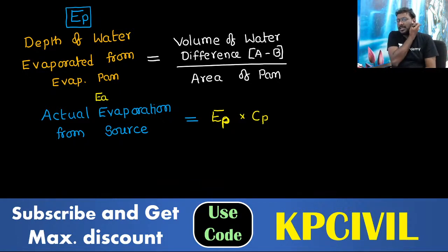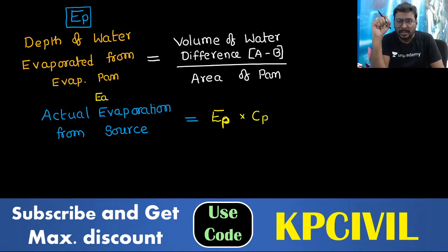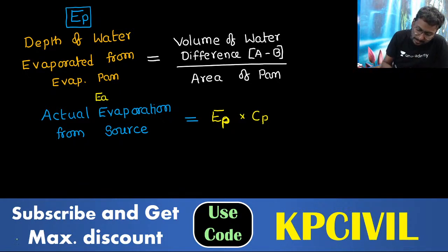Ramakrishna, pan evaporation is for a restricted area. Pan evaporation is only in the restricted area of the pan. Clear? A pan of 1.2 meter diameter. We are multiplying per unit area. Got it, Ramakrishna? We have calculated per unit area, then multiplied with the pan coefficient. What is CP? CP is the pan coefficient, the coefficient of pan.